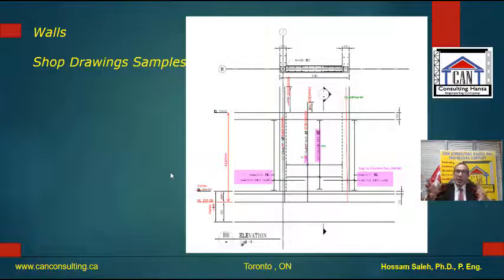Now, after you create that, as you saw, that's the design drawing. Now we are talking about the shop drawing. Shop drawing in the concrete structure means that sometimes they send us some notes about the formwork, and most of the time it should be always the rebars, but it can have some additions to it. But mainly that's the main part, reviewing the rebars. So for the rebars here, you can see this height from this level to this level has to be corrected, and the overlapping length is something you have to consider.